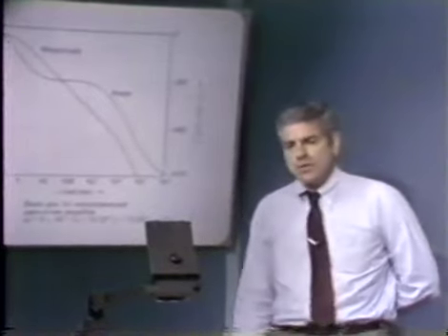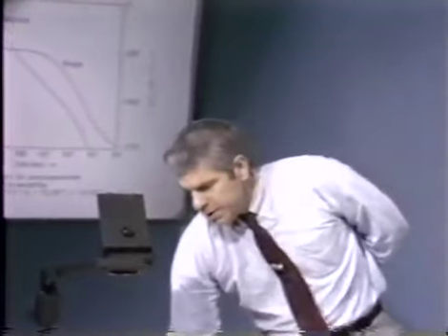So we've now concluded 2 things. One is that the original uncompensated system has minus 128 degrees of phase shift at a frequency of 6.7 times 10 to the third radians per second, and further that the magnitude of the AF product, uncompensated, at that frequency is 6.2. Well, if we follow our rule of thumb and locate the zero of the lag network a factor of 10 below the crossover frequency, we're going to make the 6.7 times 10 to the third be the compensated crossover frequency. We'll have a phase margin under those conditions of 47 degrees.